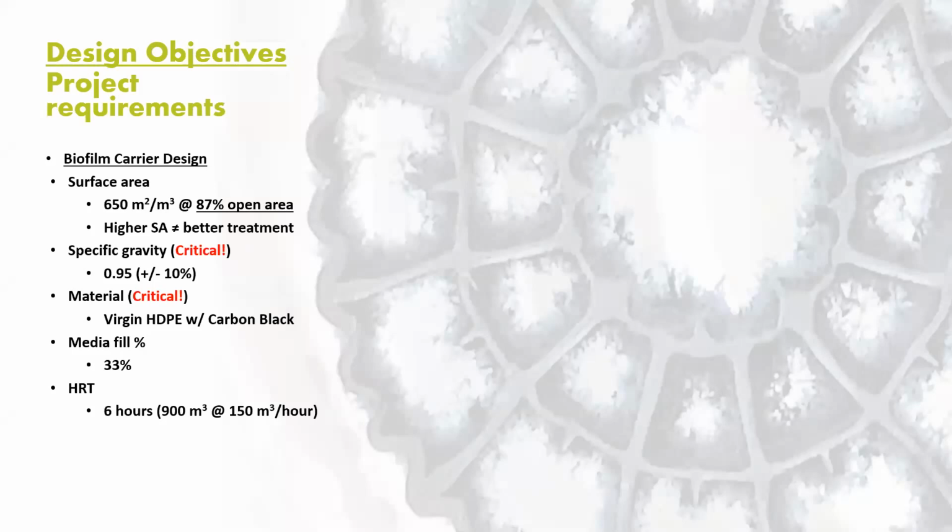The more critical factor that we looked at for this application was the open area, just based on the COD from the denim washing process and the dyeing process that they had, and based on the fibers in the system. We chose not to use a higher surface area media because we were worried about the inorganic loading over time. So here we are 4 years later, and the system is still achieving greater than 90% removal consistently. So I think the design worked out very well in this case.